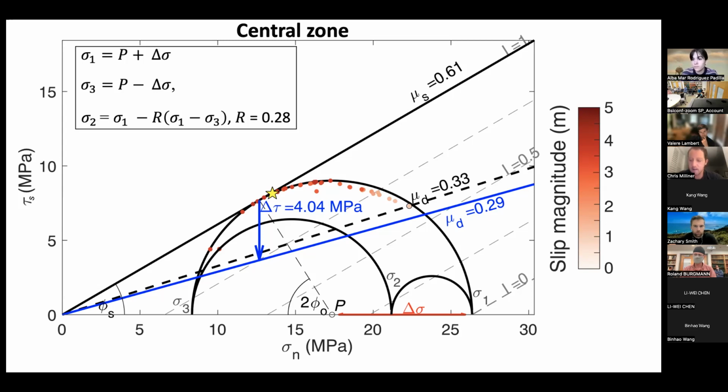The issue is that for this analysis to work, we need to calculate the maximum shear stress, and we get that from the stress rotations. And there's not a good aftershock catalog there, so it's difficult to do that. There is a good fault geometry, and there are a lot of good studies using InSAR and 3D optical data, now that we have a good constraint on the fault geometry, but it's usually those two parameters that are the biggest hurdle.